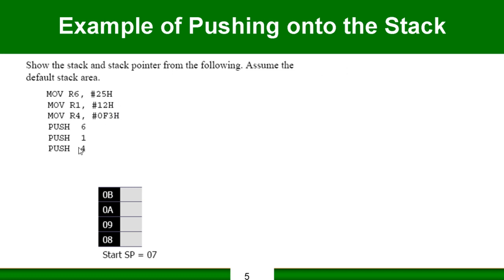As we mentioned in the previous part, the push and pop instructions use direct addressing. We cannot use the name of the register. We can only use the address of the RAM location. So whenever we perform PUSH 6, we are moving data from RAM location 6, which corresponds to the R6 register. So we can see that here we have 3 push instructions.